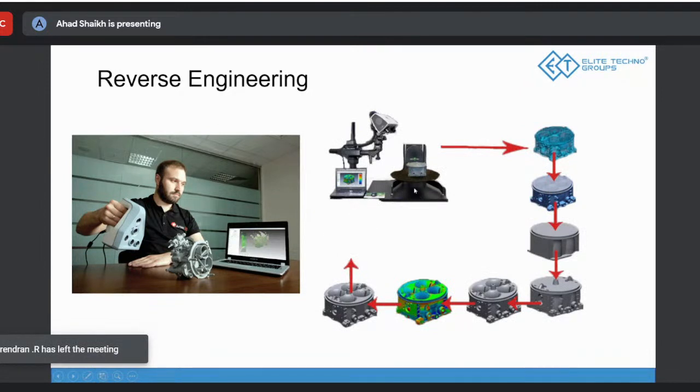Like here you can see the steps, as it's a very complex geometry. So what happens, you put it on a bench, and sometimes a rotating bench basically. I'm audible now? Yes, sir. Okay. So what you do is you put the 3D scanner, and you rotate the table, and you capture the image from the different angles, and that's how you create the surface geometry of that.